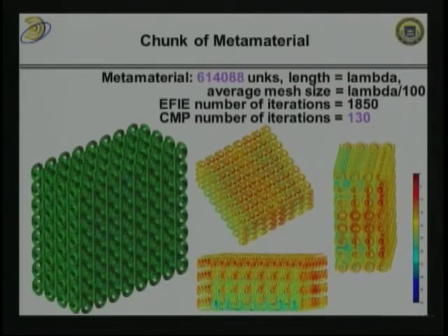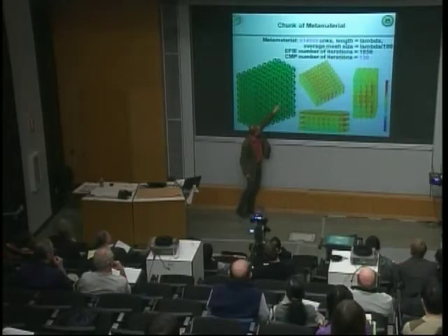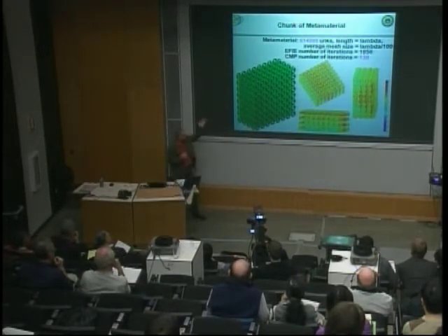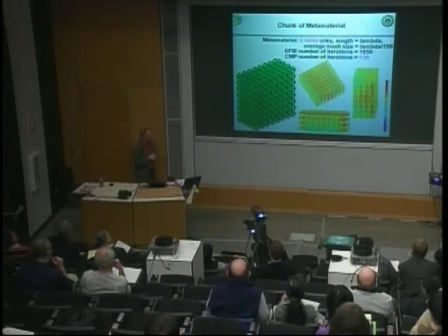Metamaterials. Now we can analyze metamaterials much faster than we could before. All these things are very, very small compared to wavelength. There are gaps here, split ring resonators, which have very, very tiny gaps, which call for very, very fine meshes. Without the Calderon preconditioner, it takes forever to converge. With these things in place, you don't worry about it, kind of.